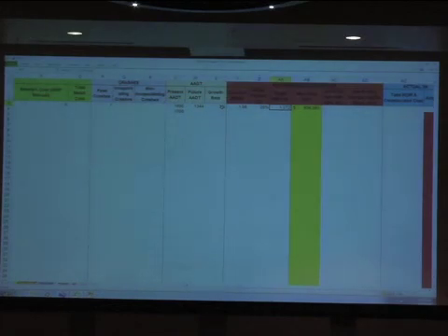Based on the target SII, the spreadsheet tells you what the maximum total cost of the project needs to be so as to meet the minimum SII. And based on that, and assuming that you know the unit cost of this specific work code, centerline texturing, what is that? Is it 10,000 approximately? So the cost to do centerline texturing per mile is 10,000, and the next cell tells you that you can do 93 miles of centerline texturing that will allow you to submit the project with an SII higher than your target SII.